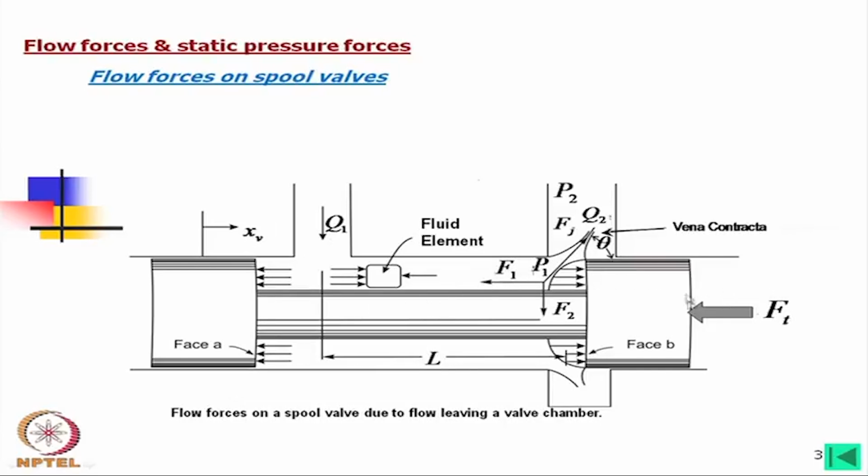Here I have assigned a force which is controlling the spool, but this force will not really have the direction shown. It might be opposite also. Why is it like that? While we are controlling the spool position, when it is opening we might give the force in one direction, but if it is overriding or over open, then the force might be in the opposite direction. And in a particular spool position, the force may act in both directions to keep the spool in that position.